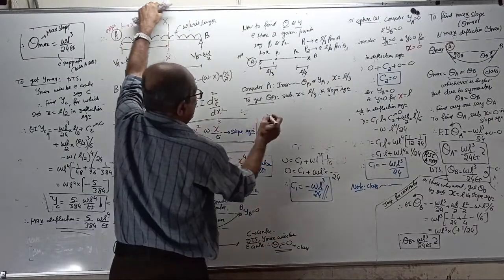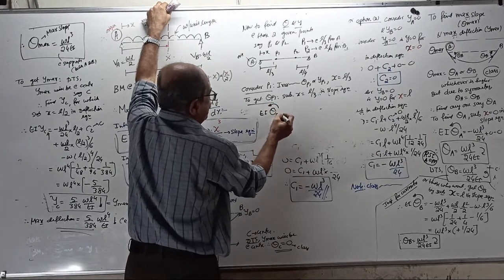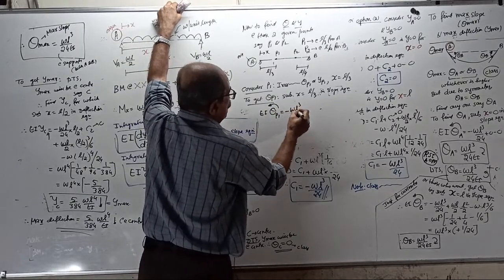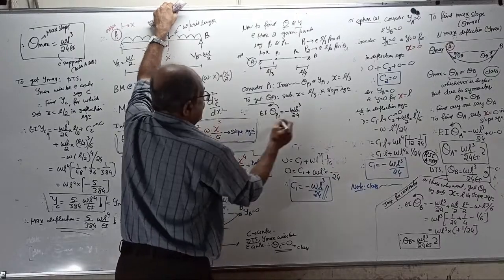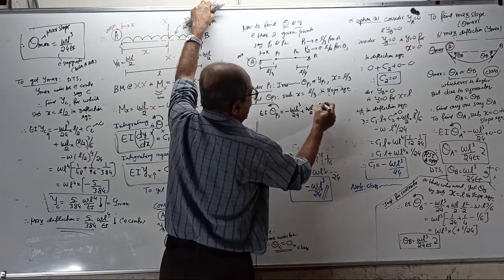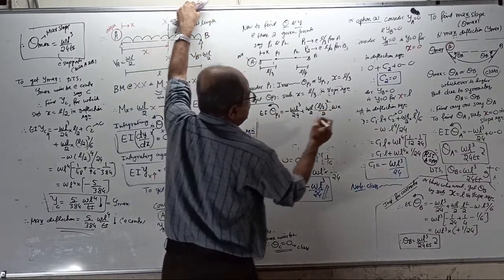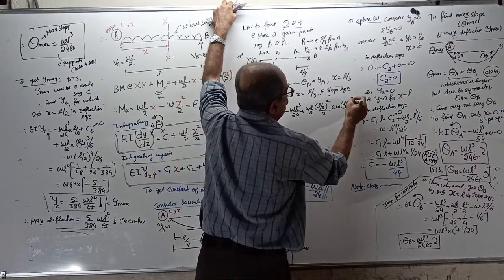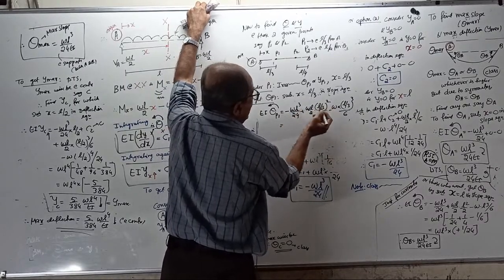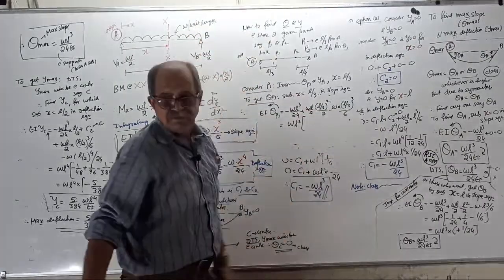Slope equation: EI theta at P1, anti-clockwise positive, equals C1, that is minus WL cube by 24, plus WL by 2 into x square by 2, that is L by 3 square divided by 2, minus W into x cube by 6, L by 3 cube divided by 6. This equals WL cube, WL into L square, WL cube. You can push WL cube outside.